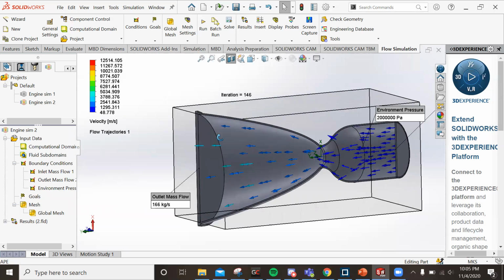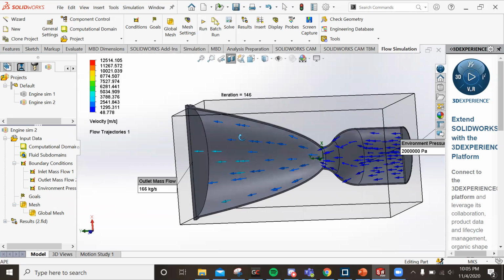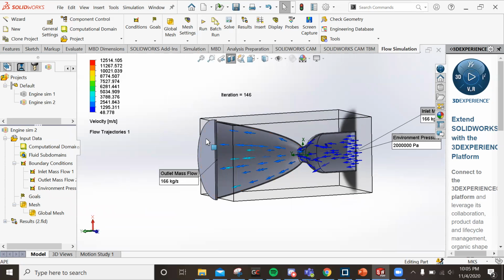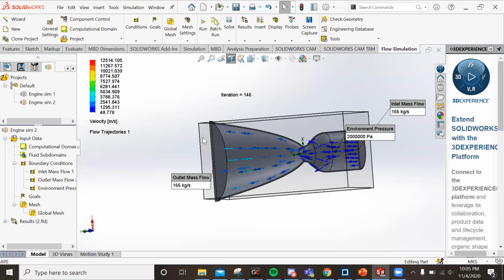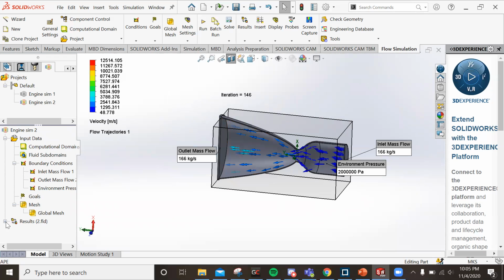And then if you finish this sim, because you already know how to use SolidWorks FlowSim, another thing you can do is change the boundary conditions over here. Instead of just capping the end of the nozzle, you can put a giant cylinder around it and let it essentially shoot the nozzle's exhaust into open air-ish, kind of, by doing a giant cylinder.